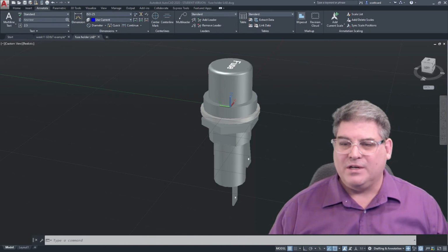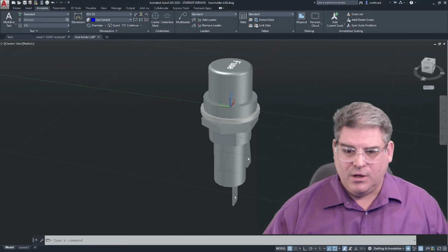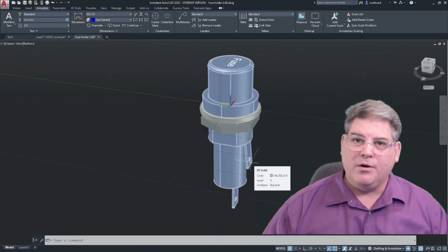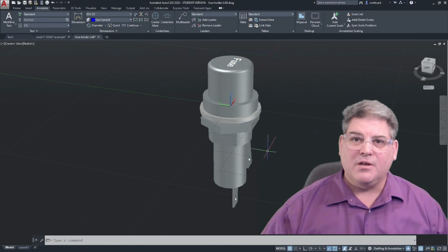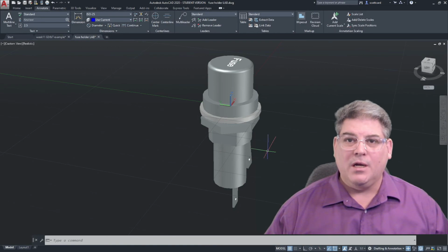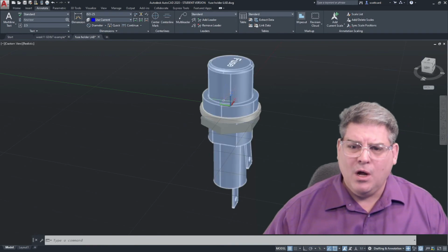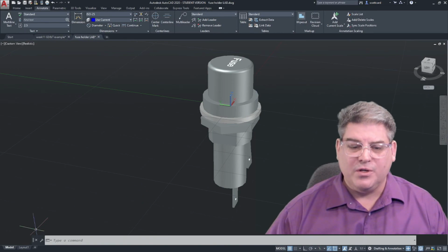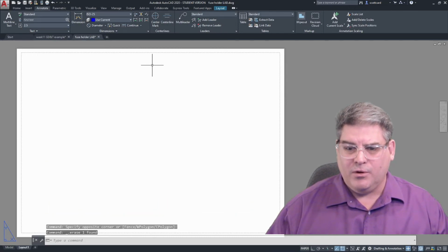And so here is another example where I have a hole on a feature that I would like to have a dimension on. I'm going to show you a couple of other little features on how to dimension this and do a layout that is really quite nice. The first thing is, don't just open the file the way I have here. I want you to import it into your standard drawing so that you can get your border and your title block.